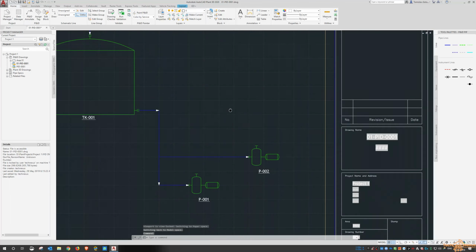Okay, and then I'm going to run the discharge. Same thing, I'm just going to run it up to a point, stick my off-page connector there, and it looks like it's in a good spot, so I don't need to bother stretching or moving things around. And then again, same thing with the primary line segment going from the pump to the header, and you can see that it's its own separate line.